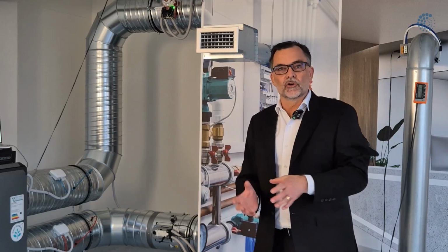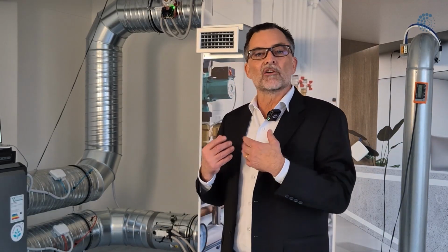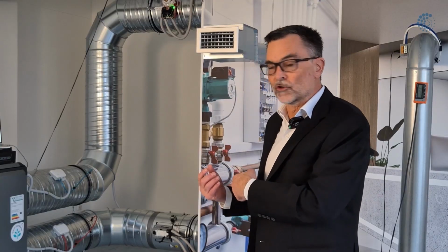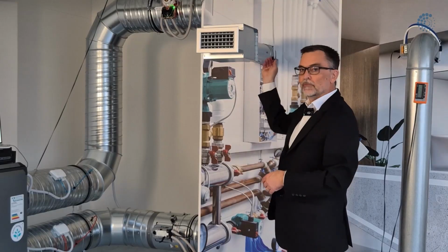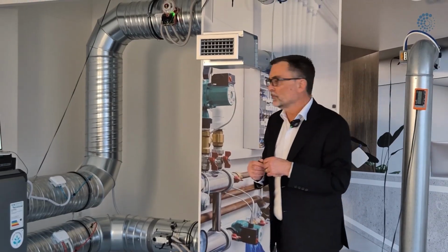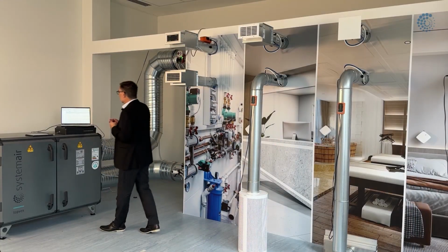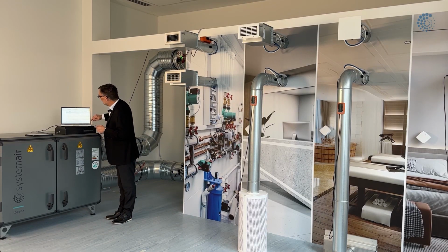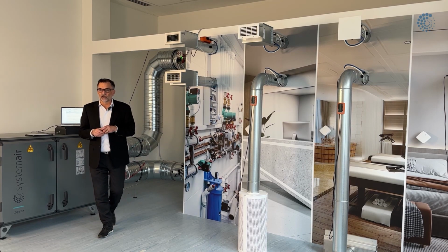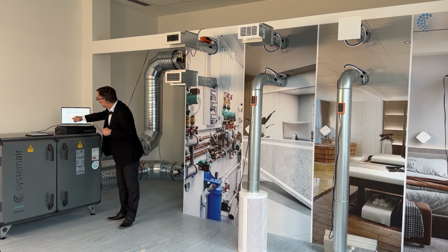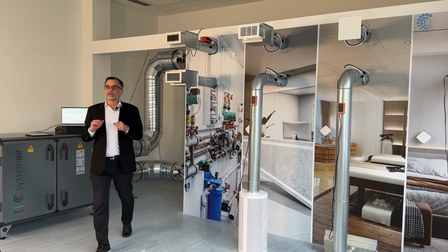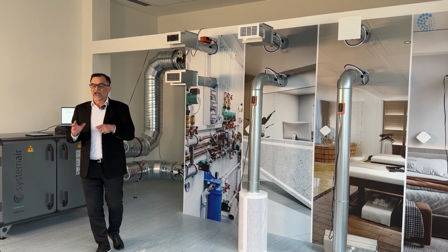Our bag storage room has a pressure differential system, which means we are under negative pressure in our storage room. So let's simulate that by opening the door to the technical room. What you can see here is we normally keep about 60% less air volume, which means we would like to keep minus 15 Pascal pressure.